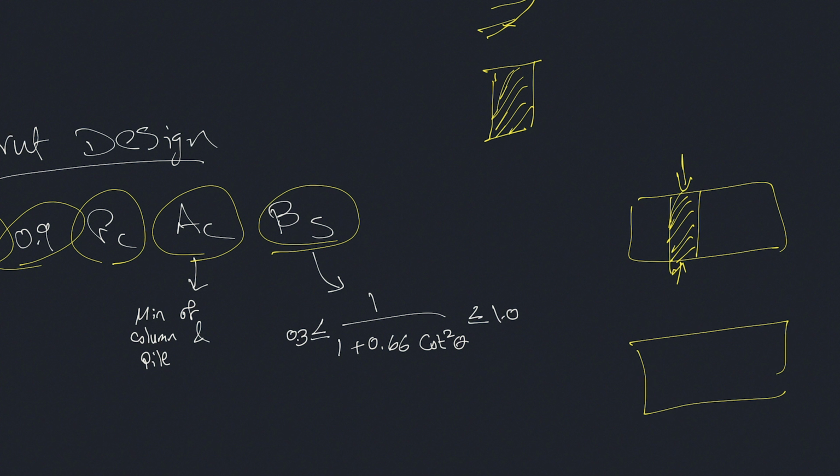And it also takes into account that if you have a very steep angle of the concrete, like in this angle, the concrete actually starts to fail in splitting. And because of this method of failure, you get a much reduced capacity. Because when it's inclined at a bigger angle, the concrete cannot mobilize as much capacity as it can when it's fully vertical, this efficiency factor reflects that.